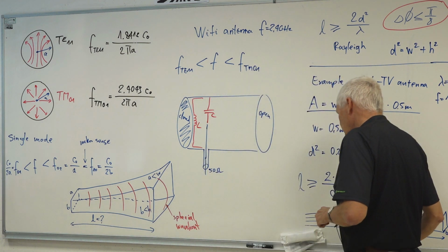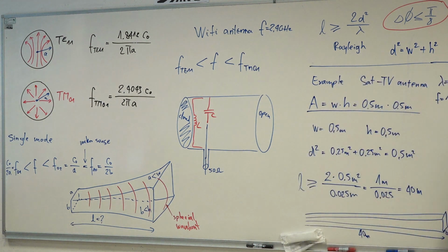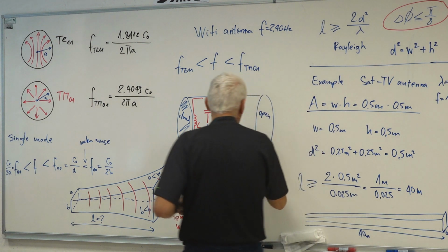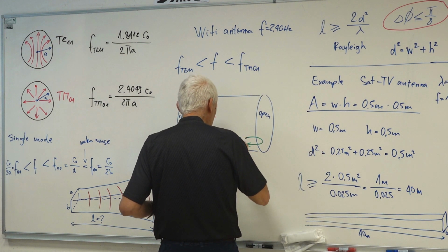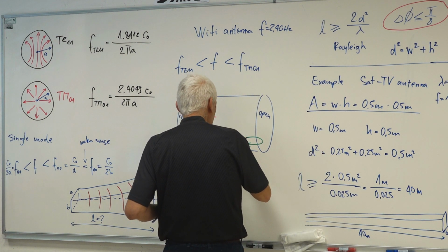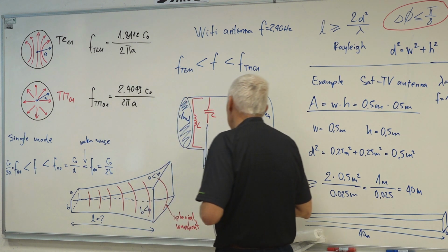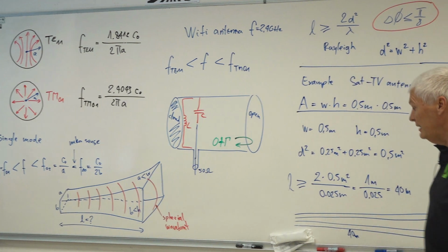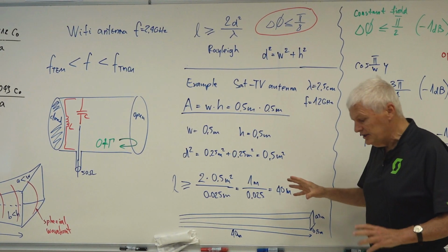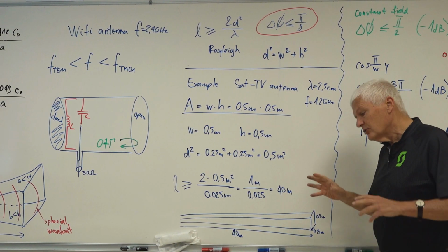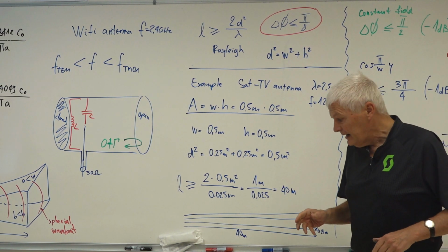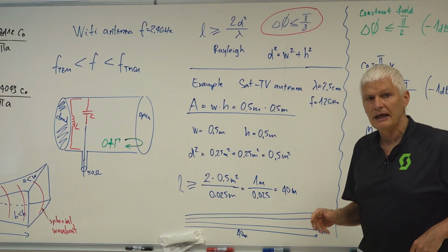And of course, what I should not forget is that at the open end, I have some reflection. This gamma is different from 0. So this reflection will also affect the impedance a little bit. So it's a little bit tricky to get all the dimensions from a standard coffee can to get good impedance matching. But I believe your students have the time to do that.